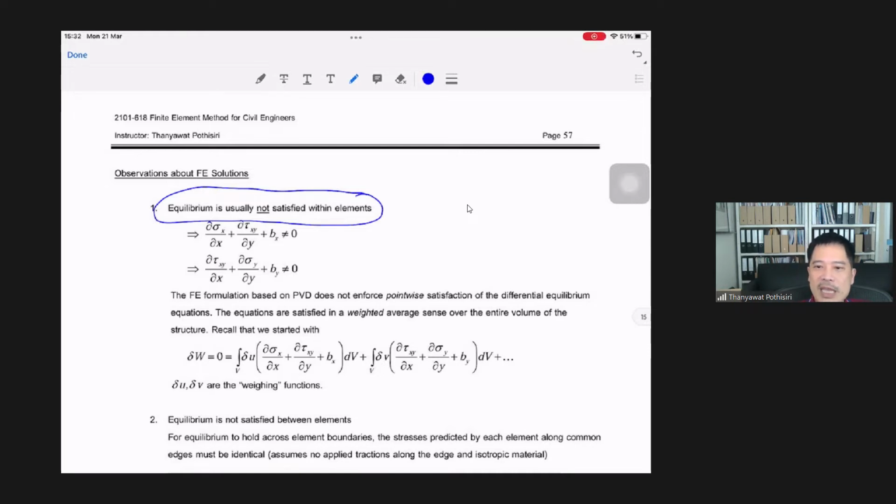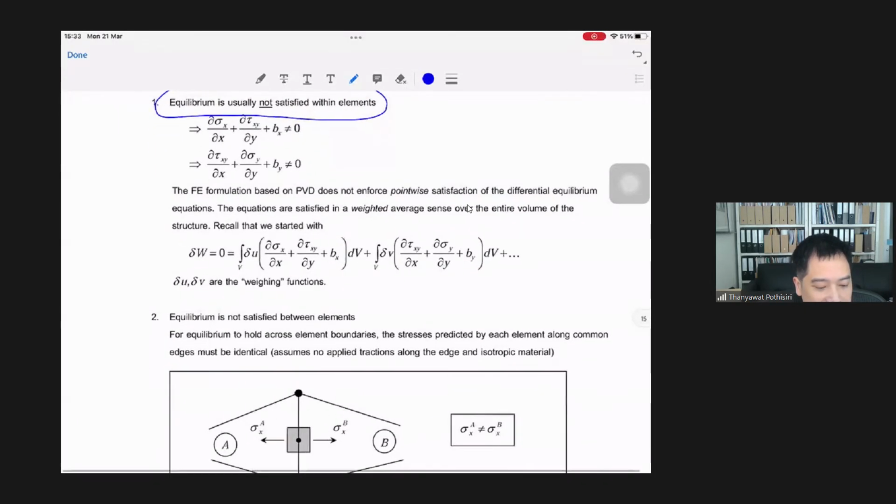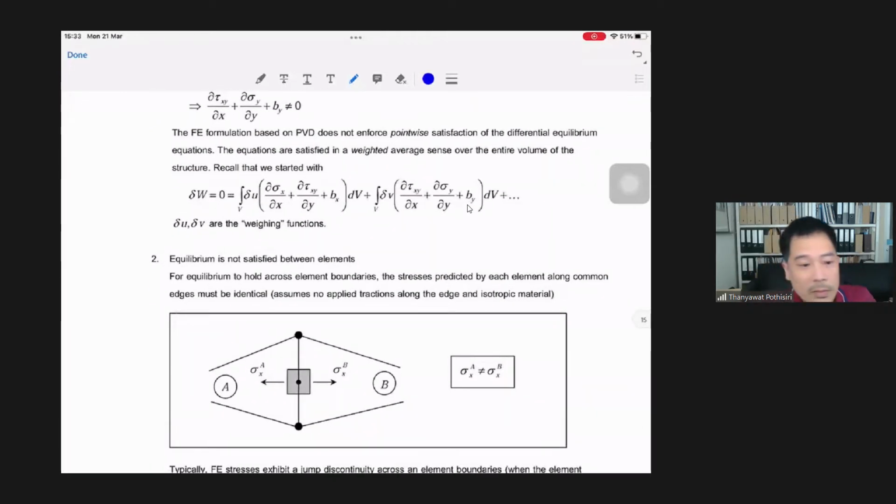So how can we be certain that this problem would be minimized? What we can do is monitor these errors or discrepancies by using quantities that we know would exist. For example, we know that across element boundaries, stress and strain jumps can exist.